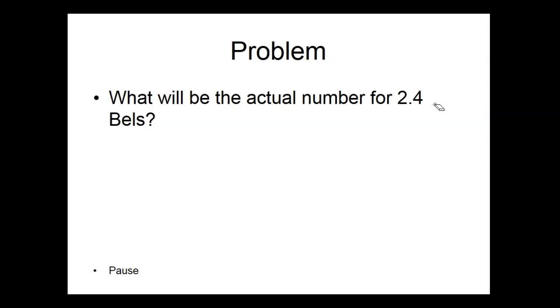But if I wanted to get it back to the number, I just take the number and move the decimal point one place to the left, and then I would come back up and use my 10 to the x. So we always shift it one time, either left or right. In engineering notation, you have to remember 3 places for milli and 6 places for micro. But in dB, we shift it one time to the left or one time to the right. And we call it dB. And we round.